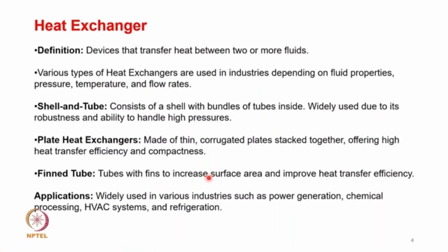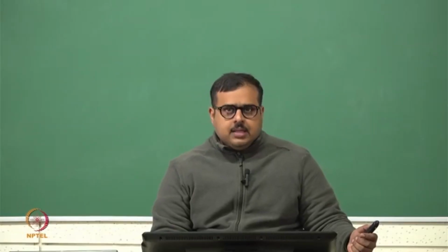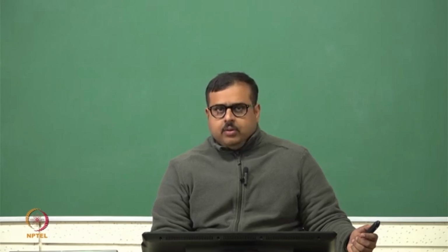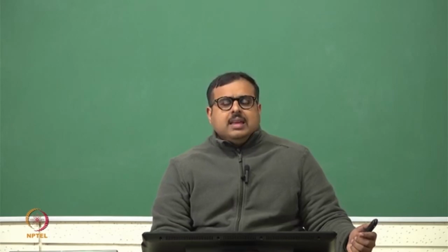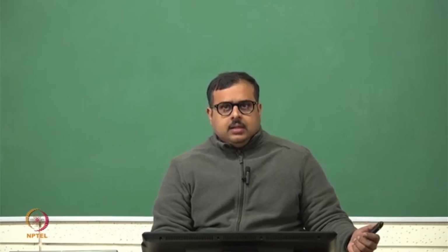And of course, there are many others. The third example that I would like to speak about is the finned tube. Tubes with fins typically increase the surface area, and eventually that would improve the heat transfer efficiency. The fins are projections on the tube which increase the surface area of heat transfer. Just recall that in all our heat transfer expressions, be it conduction, convection, or even radiation, area is one of the key parameters in the expression.